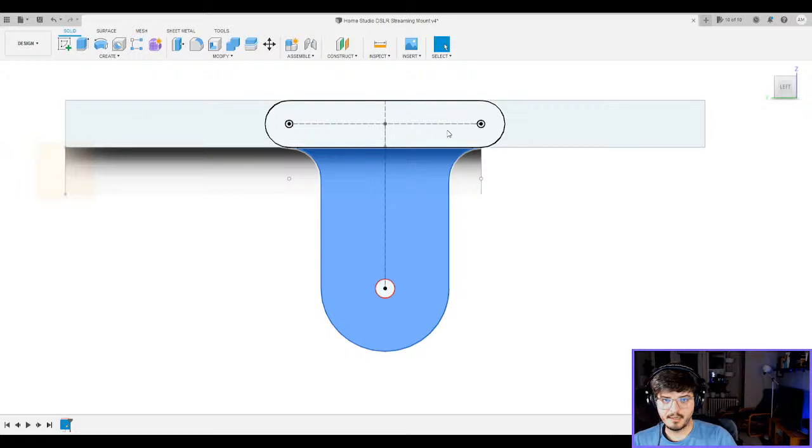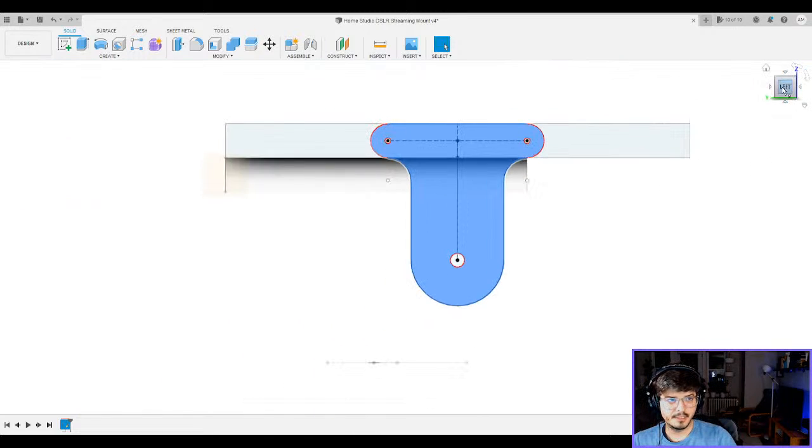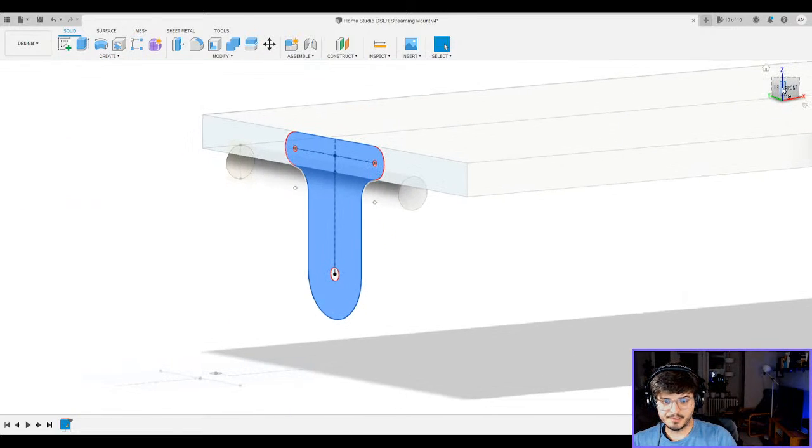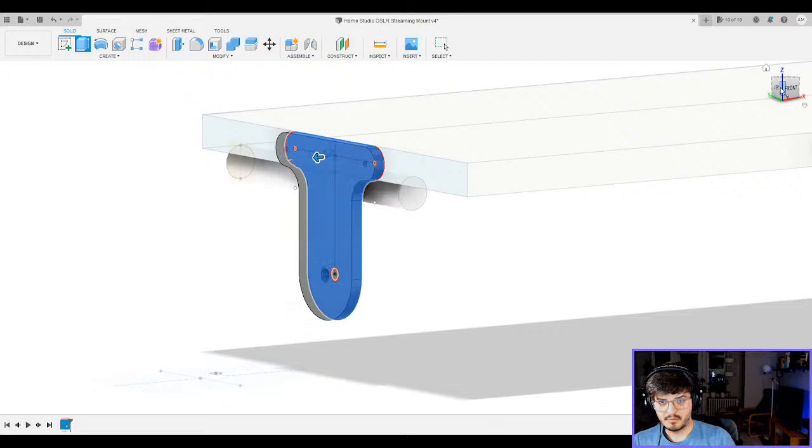I'm going to use that geometry. Click and click. I'm going to rotate this just so everyone can see, and we're going to extrude it. How thick are we going to extrude this? I was saying 1/4 inch might be nice. Should I do more? So it's like a 1/4 inch plate at this point. That's basically what I'm making this.